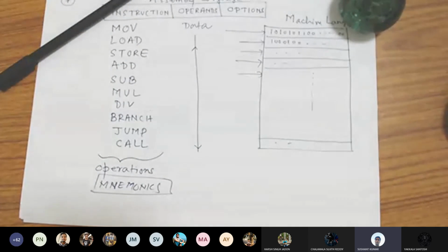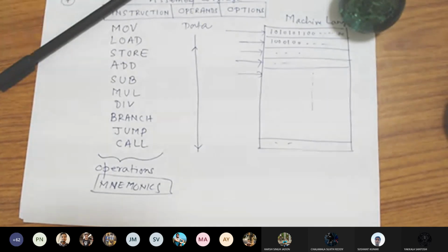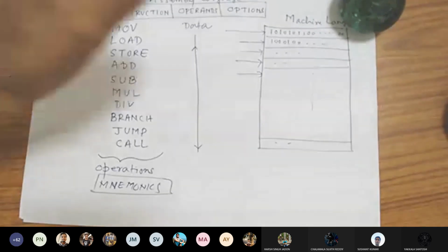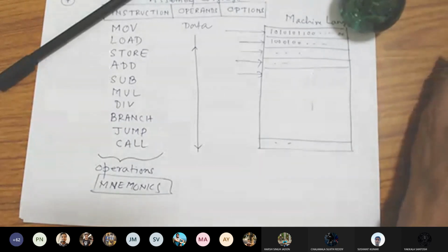Sir, last time I was thinking we have to implement the multiplexer by ourselves, which would be a complicated circuit for 32 bits. We can just use the inbuilt muxes of Logisim. Right, you can just use the inbuilt muxes which are available there, and you can define their input width, output width, and data line width. That's why, when you look into Logisim, you see which components are already available. There is no point in designing a mux, because multiplexers, demultiplexers, decoders, and encoders are already available, unless you require a specific mux. Otherwise, you can use the existing modules available as a library. Why spend time designing those simple things? Yes, sir.